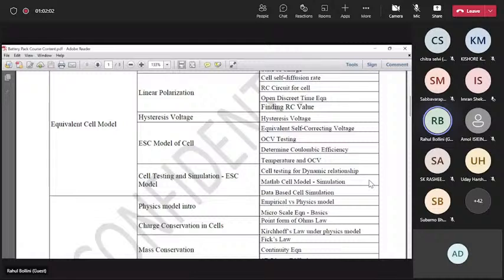That is where BTMS comes in, battery thermal management, to actively dissipate heat. The sizing of BTMS matters a lot, and the cell should not experience heat for a long time. There's liquid cooling and all that; I'll be talking about it in the next module. But generally, we'll be talking about the temperatures, and there's some physics-based model, which is mostly theory, but I'm more of a practical person. So we'll talk about C rating, like I told.